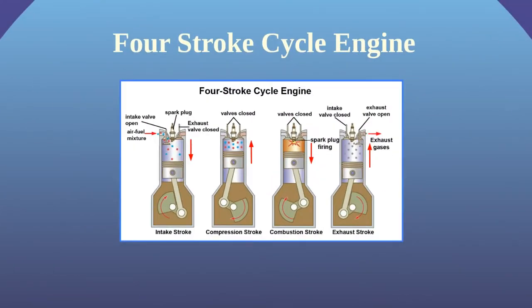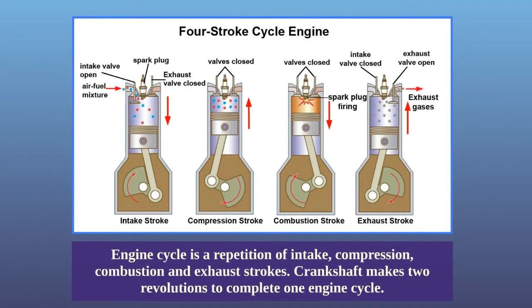4-stroke cycle engine. Engine cycle is a repetition of intake, compression, combustion, and exhaust strokes. The crankshaft makes 2 revolutions to complete one engine cycle.